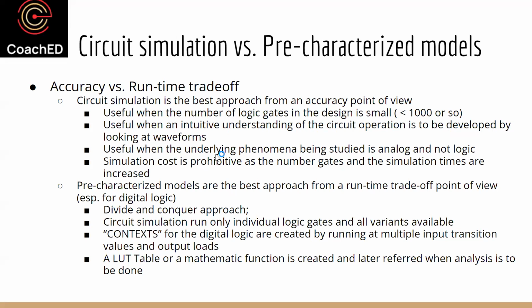Especially if you want to study some phenomena which is analog, let's say if you want to see the effect of currents, the effect of power supplies, the effect of glitching, or the effect of power and so on, and not logic, then certainly you cannot do without circuit simulation. But simulation cost is prohibitive. It's very expensive, and therefore, unless your number of gates is manageable, people avoid running circuit simulation.